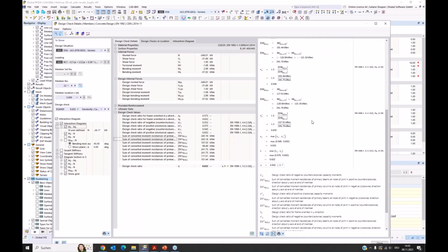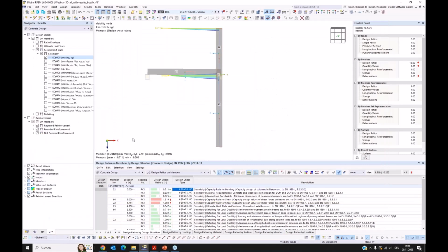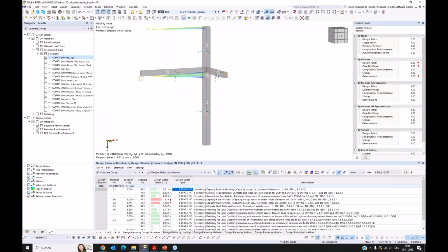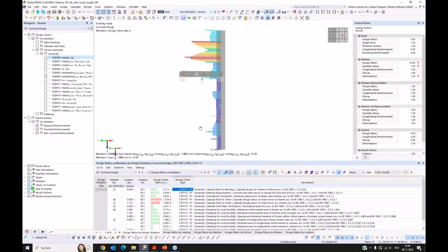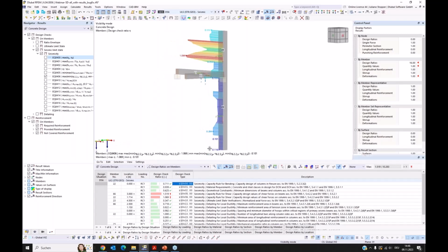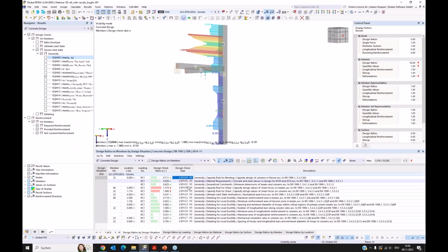Okay, that's it for the check of the strong column weak beam, or the EQ400. Then we have, as we spoke about, here you can see that the 66 is relevant for the Z direction. Then we can check the shear force from the shear check for capacity design. It's for columns in our program the 0406 design check, but you can also read it here in the description.